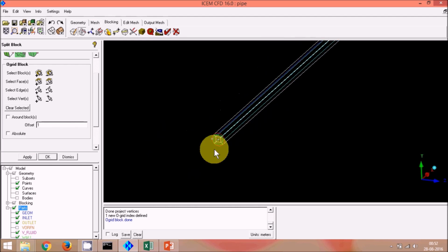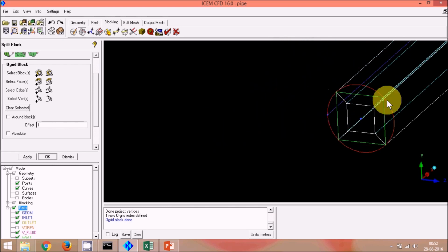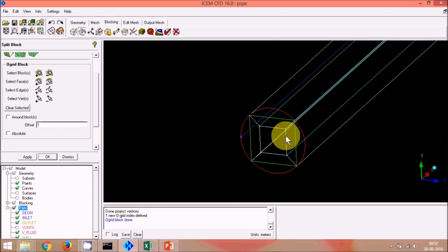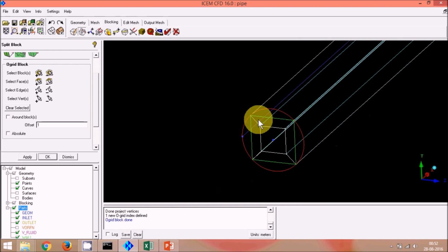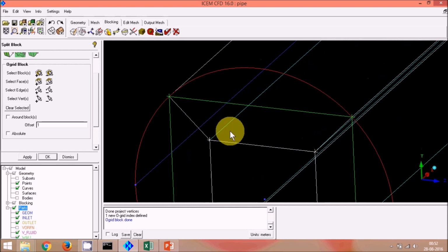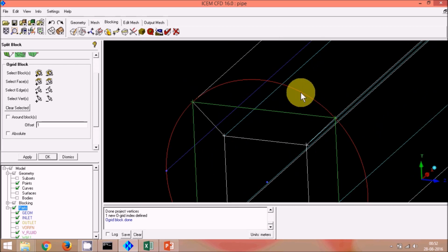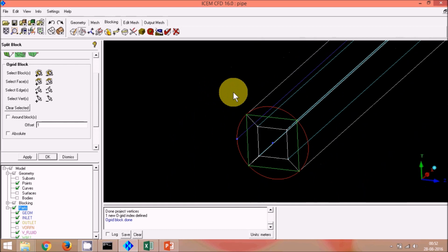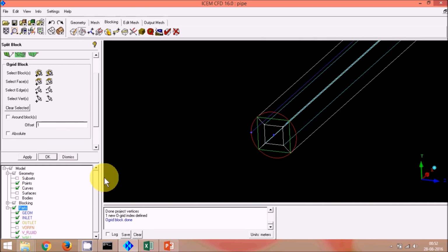That is, you see, you can understand and appreciate what is O-grid now. See, initially there was no such thing running diagonally, and there was not a square block inside. Only one complete outside block was there. It was not enough to define the mesh parameters accurately. If you have a diagonal thing, you can define the mesh fineness near the walls and those sort of things. Okay, now let's get on with the mesh parameters definition.